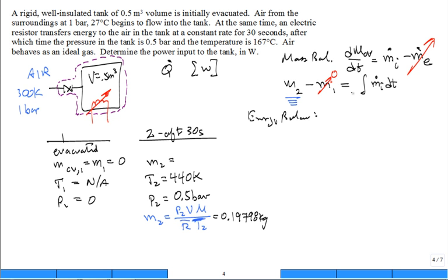All right, so the rate of change of energy in the control volume with respect to time is equal to the rate at which it's flowing in with heat, minus out with shaft work. And we're going to say mass comes in, bringing with it its enthalpy. I'm neglecting kinetic and potential energy coming in, minus the mass flow rate exiting, taking away its enthalpy.